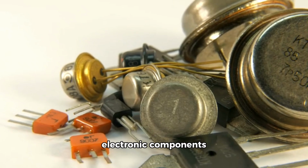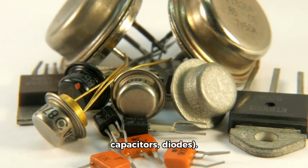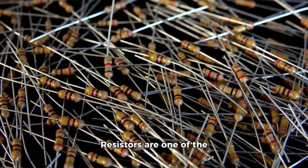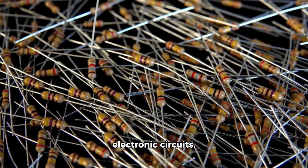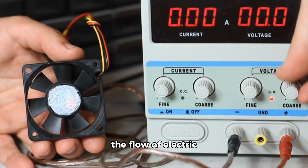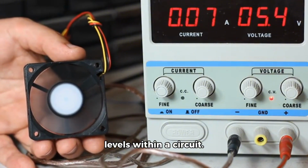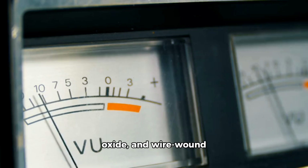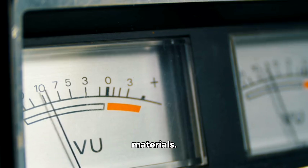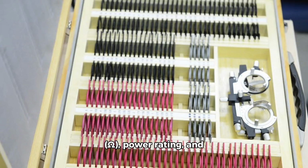Introduction to electronic components and devices, for example, resistors, capacitors, diodes. Resistors are one of the simplest, yet most essential components in electronic circuits. They offer resistance to the flow of electric current, allowing control over current levels within a circuit. Resistors are made from various materials such as carbon, metal oxide, and wire wound materials. They are characterized by their resistance value, measured in ohms (Ω), power rating, and tolerance.